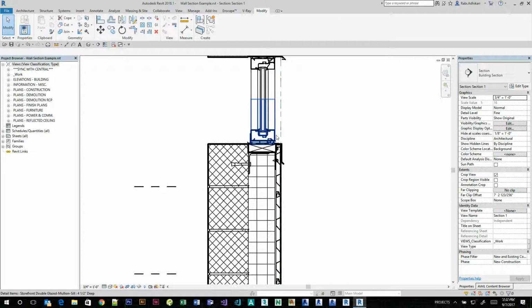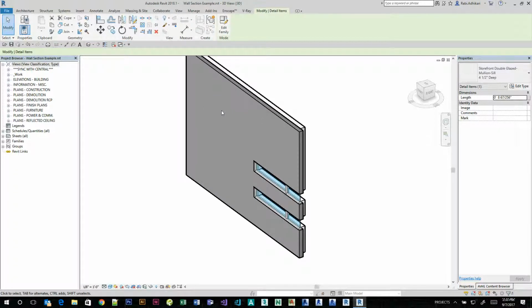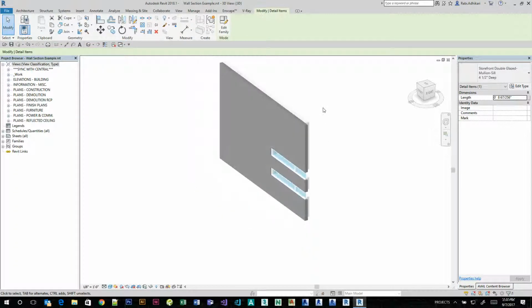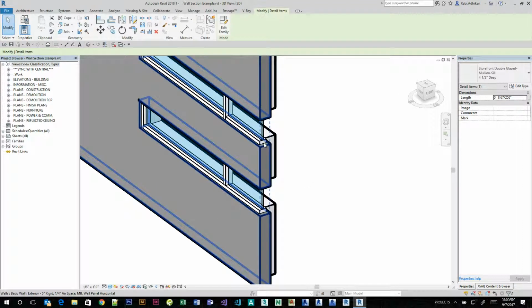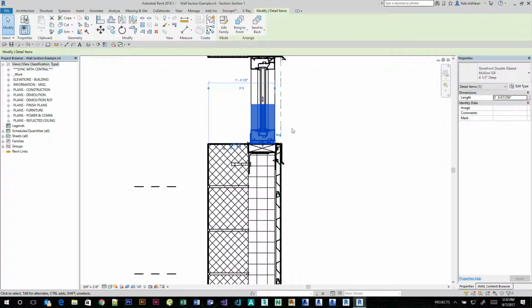Another key element we spend a lot of time on is the window or curtain wall system. As an example, let's take a look at the system here. I have focused on establishing the volumetric representation of the aluminum profile we see from outside and the glass relationship with the front. The rest of the items and details shown in the section are detail items.